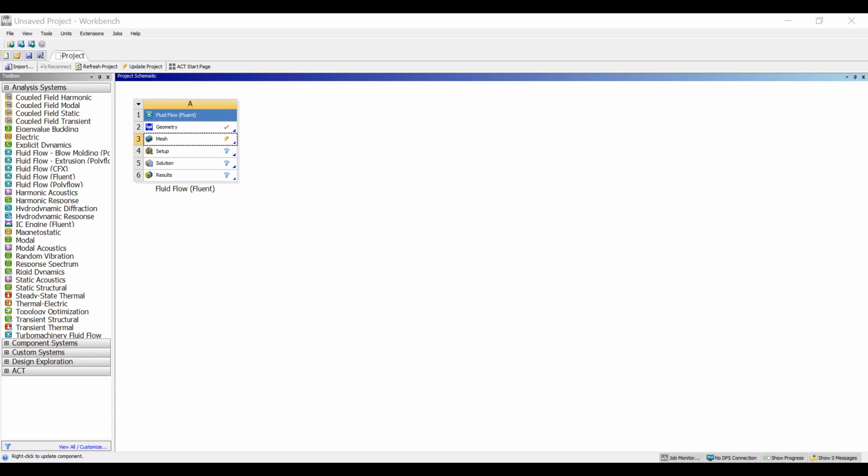And now you can see we've got a well-defined mesh here right around the boundary of our circle or our simulated cylinder, circle in 2 dimensions. And so the last thing we're going to do with our mesh before we close out of this is we're going to refine that mesh a little bit more. So our element size is currently just under the standard default, which is about like 3. So we're going to go ahead and refine this much, much more. We're going to go ahead and do 0.2. And let's generate that. That's going to take a little while. We'll go ahead and load that up.